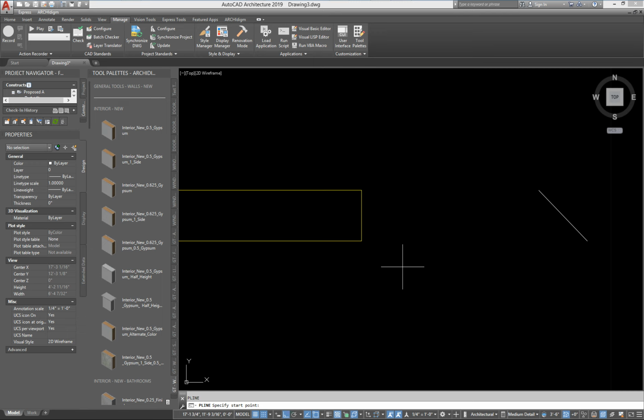I'm going to use P line. So to keep out of trouble, even though there are cases where you can use the line for just straight segments, use polyline. It's the best way to keep yourself from getting into things that won't work, because polyline reads as one continuous thing. So in this case, I would have to use a polyline. I'm going to start here. I'm going to put my angle on, and I'm going to O-track over like this, like I did before, 315.